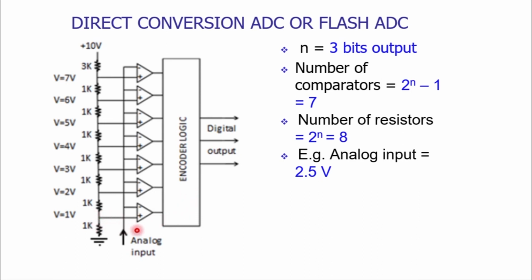So this comparator we are setting at the least priority, and the upper comparators we are setting at the highest priority. Since the lowermost comparator has the least priority, the next comparator, that is comparator number 2, which has the high level, would be considered, and the high output at comparator number 1 will be ignored, as we have seen in the priority encoder in our previous slide.